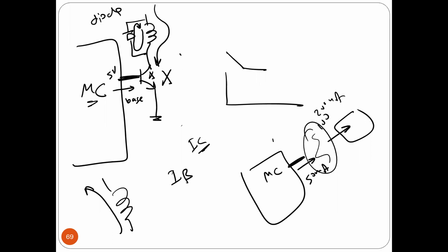Any questions, guys? Again, almost everything I taught today is not microcontroller, it's electronics, but it's very important because I'm quite sure you are going to need it in your capstone. So usually we put a diode here for protection, so that it discharges when you turn the transistor off. Okay, guys, any questions?